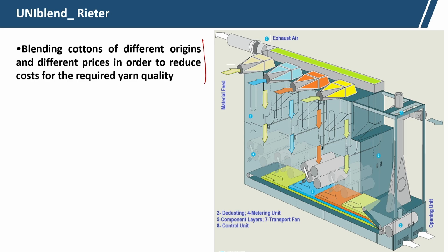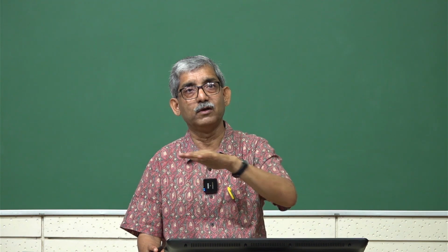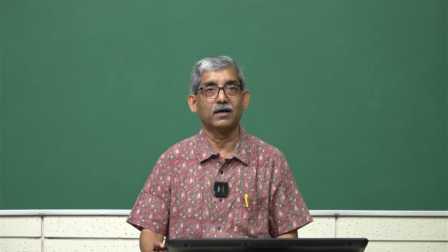Blend precision is very good. If you have high precision, then in every cross section we will get proper equal blending. If there is unevenness or a cluster of weaker fiber, the quality will deteriorate, because breakage may take place at that point. If the blend is consistent throughout the yarn, then the overall quality will be maintained, even if we are using inferior cotton.